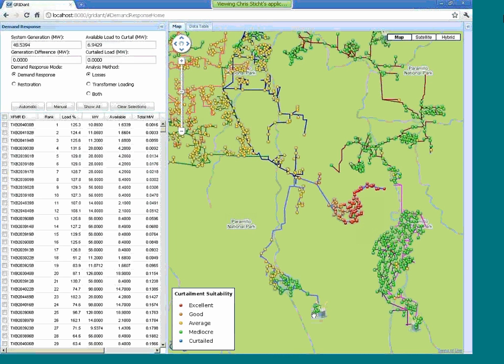So as Surya had pointed out before, if you're at the substation, there's very little line loss associated with serving a customer right there. Whereas if you have to serve a customer at the very end of the feeder, there's all the line and equipment between the substation and the customer consuming part of that power, which adds up to quite a bit.